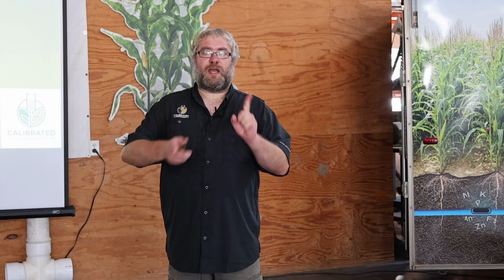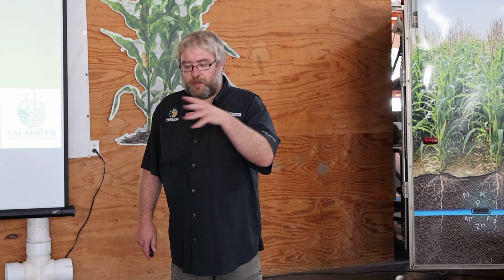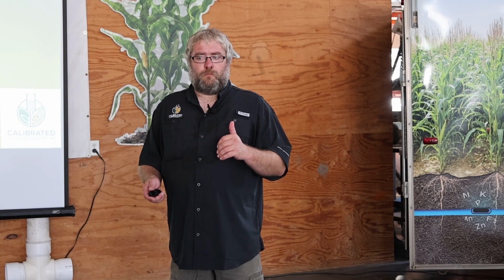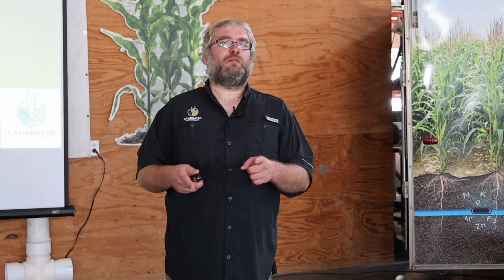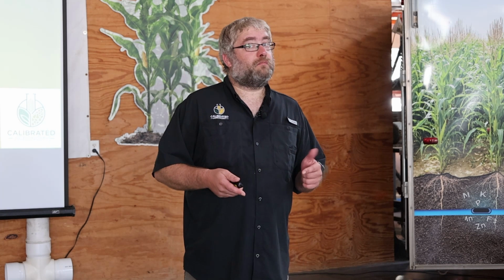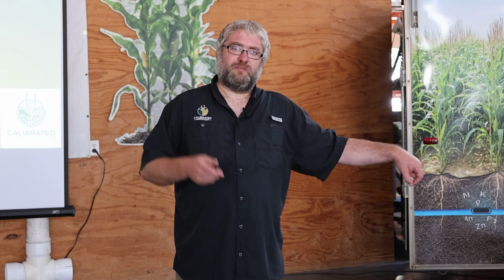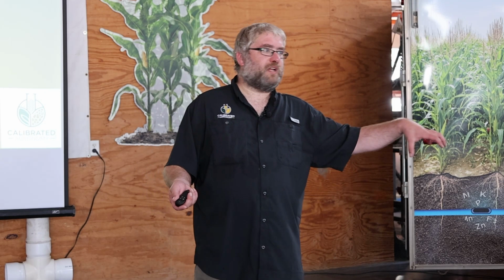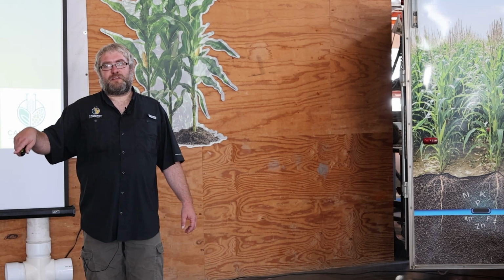We compare that DI to the irrigation water. And that brings up another good point. If you've been watering over and over and you just now identified this, how you can identify if you've got a buildup issue, and we see this with sodium a lot, is to pull the dry corner versus the irrigation. We've done that quite a bit. The dry corners never got the irrigation water, and then we look at it underneath the pivot.